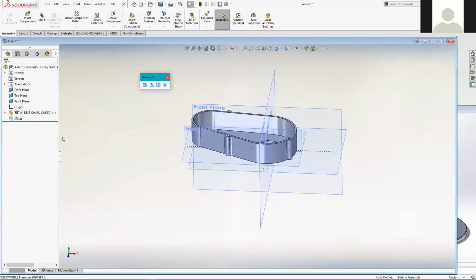So the other method that I just warned you against, where you just click somewhere in the window, what the system then does is wherever your pointer happens to be in the assembly environment, it drops a copy of the part right there. So that has normally no significance at all. It's just wherever your pointer happens to be at that point. And it fixes it in position there. So the big headache then can be later on down the line, if you want to position this assembly inside another assembly, the base planes in this assembly bear no relation to where the parts are positioned within it. So always click on that green tick on the top left to position your first part.